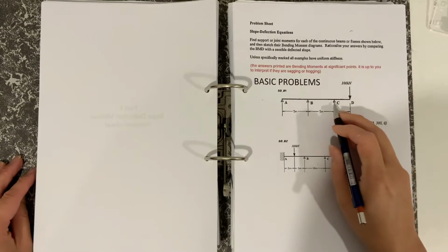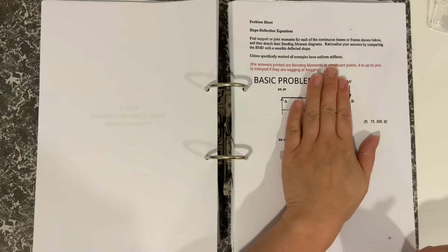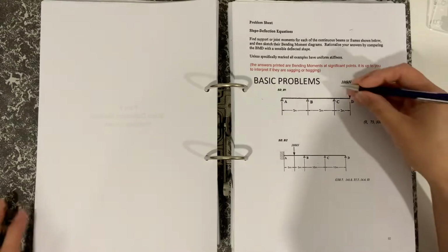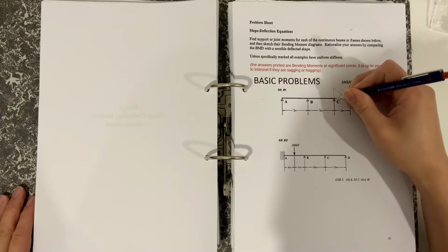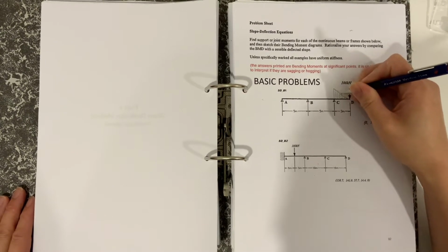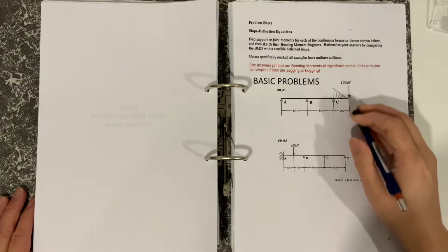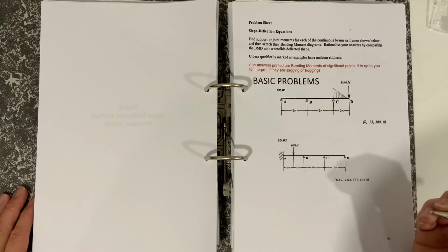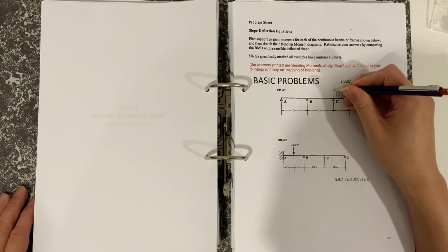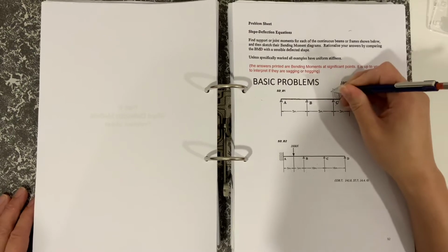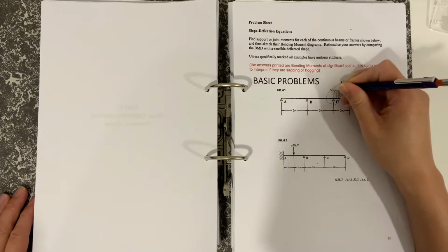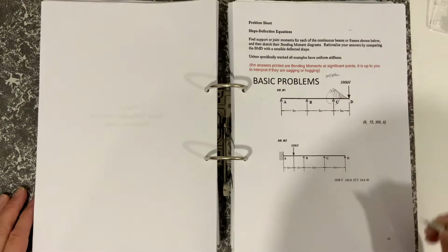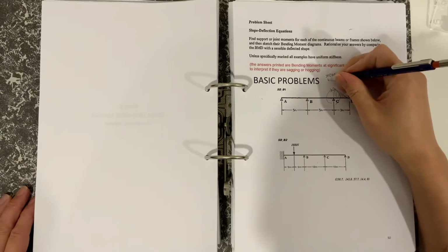If you imagine you've got a cantilever beam, just moving your way in from this side here, then you would probably be able to say that the bending moment diagram is going to look something like that, triangular going along there. So you don't need to calculate that using the slope deflection method. It's 100 times 3, which would be 300 kilonewton meters, and then we would put that arrow there, and then put that arrow on that side there. So that would be 300 kilonewton meters, and because they're going upwards like that, I'll put hogging.